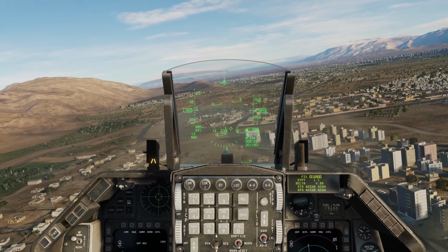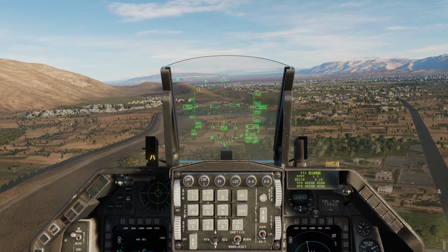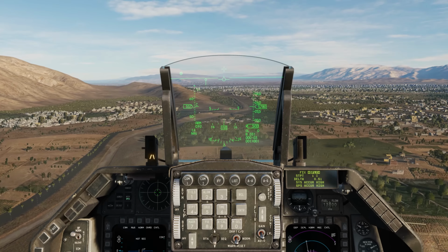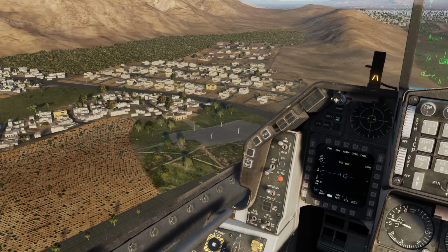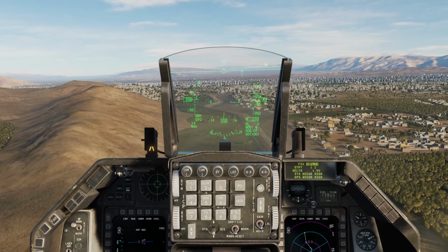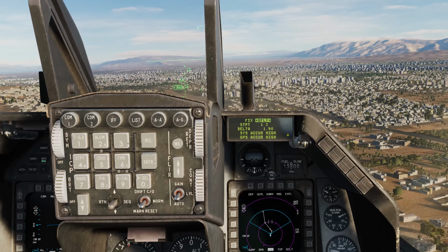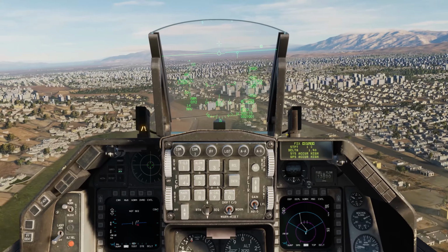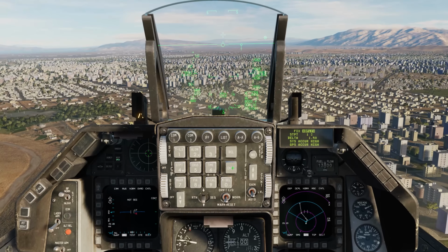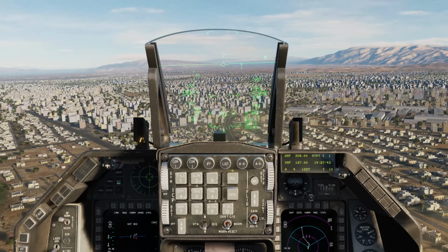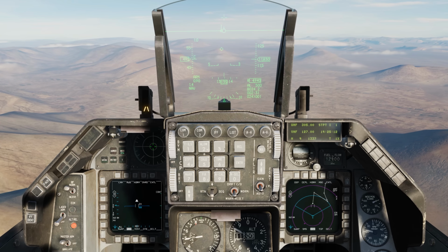Up ahead is the second bridge, and that's going to be the true location of this example for steer point 1. Again, right when I'm on top of it, I'll go TMS forward right about now. And now we can see a delta of 1.4 nautical miles. And if we like that, I can hit enter on the ICP to save that location as steer point 1. Done.